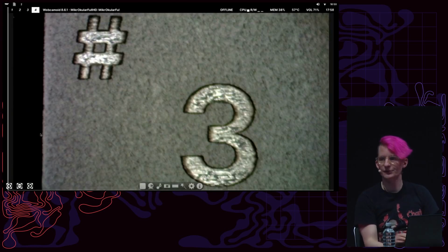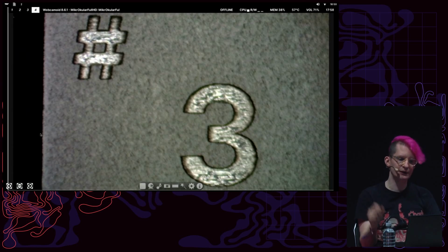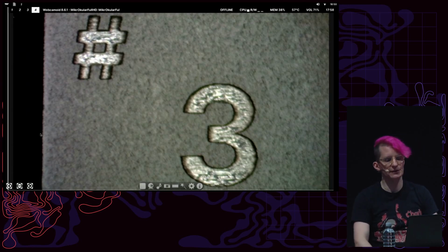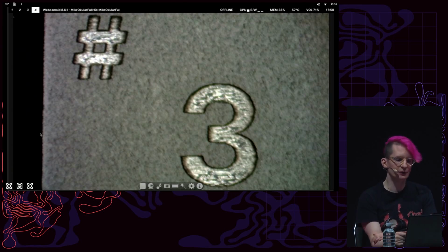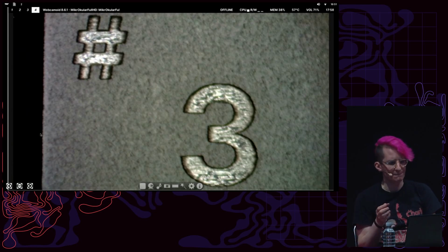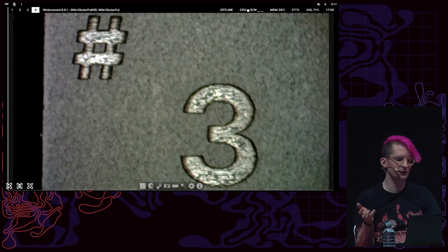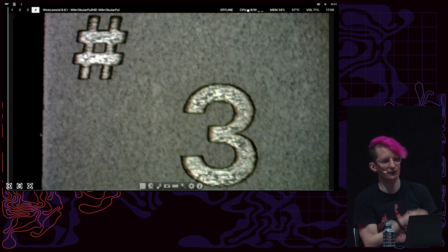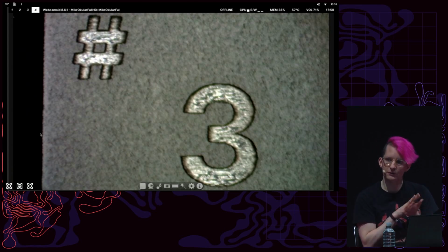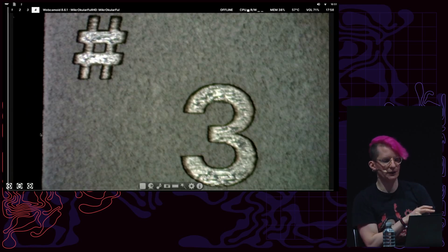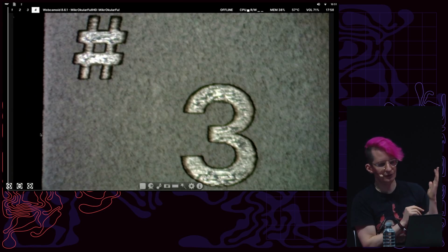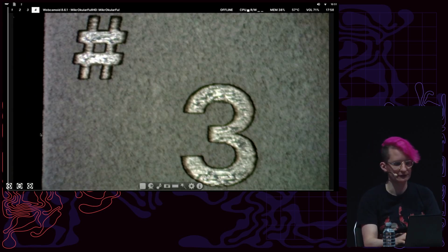A similar thing happened with the keycaps. We tried so many DIY things, and they were just not good enough to make sense for an enjoyable laptop. So we partnered with a small team of people who are obsessed with keycap molding, FK caps. We managed to coordinate a group buy with them of several keycap manufacturers, where the keycaps would be injection molded from translucent ABS and then painted with a black PU coat. We can then selectively remove parts of the coat with our laser engraver to label the caps in a durable way. That also works well with backlighting through the cap.